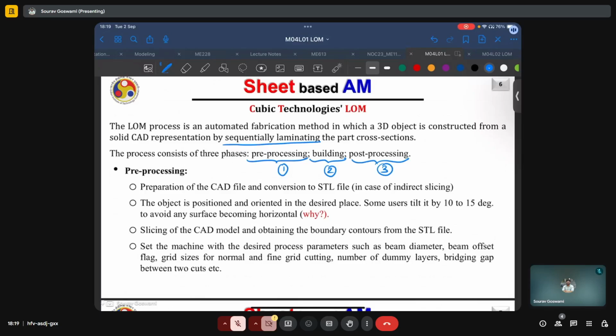Thus, in every slice, the contour that we end up with is an exact representation of the original geometry from which it is derived. A second way, which is of course far more commonly used and seen in commercialized additive manufacturing technologies, is the intermediate conversion of that exact geometry to an STL file, which is easier to handle, easier to manipulate, has well-defined methods for, say, finding and calculating support structures, and is very well adapted and researched.